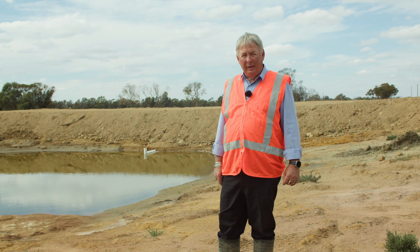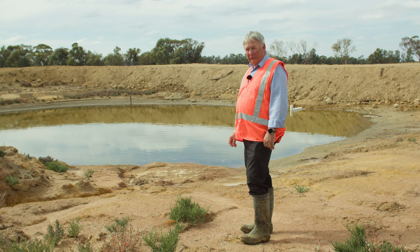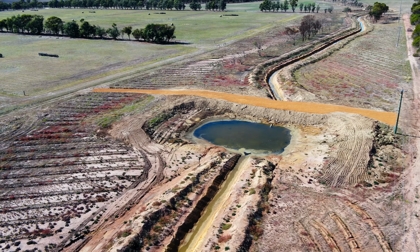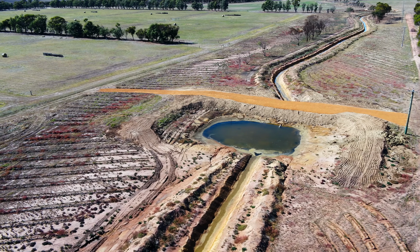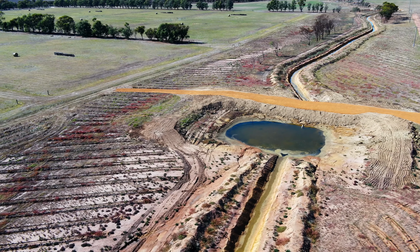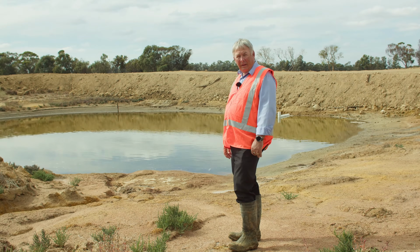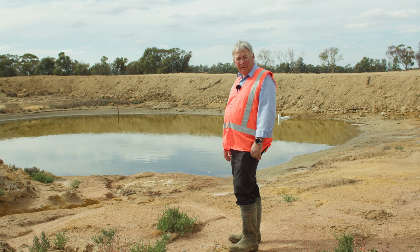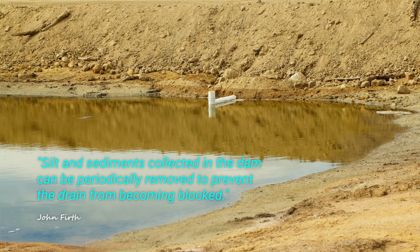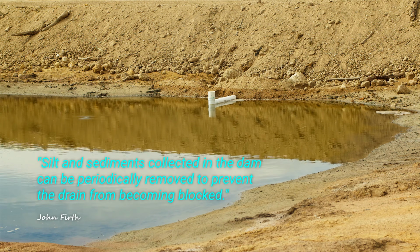This was a saline dam, and what we've done now, we've turned it into a detention dam and a silt pit at the same time. We use it as a silt pit to collect any surface water flow sediments, like this here, flowing into the dam, or any sediments coming out of the drain itself. It's used as a detention dam because in a flood situation we may have excess surface water flowing into the dam. The dam acts as a short-term storage, and the pipe over there will actually take the water out of the dam back to its original level.